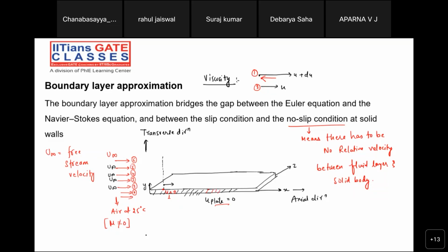And if I'm at rest conditions, you know that we have a lot of bonding with each other. Yes or no? Viscosity, if I just talk in terms of liquid, what is the reason for the viscosity? Cohesive forces, right? That means there are a lot of bonding forces between the fluid elements. If there is bonding, then how can the second fluid layer move with the same velocity u infinity? It has to move with somewhat lesser velocity. Is that clear now?